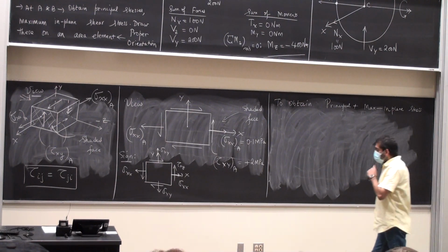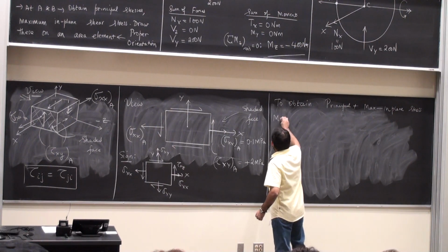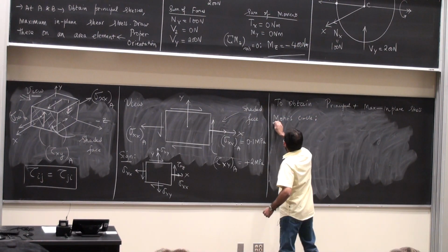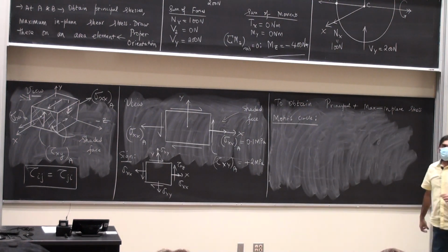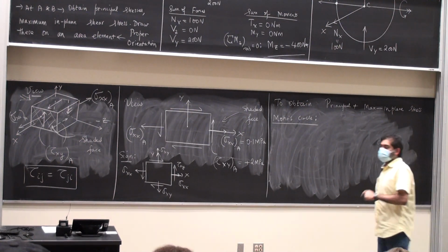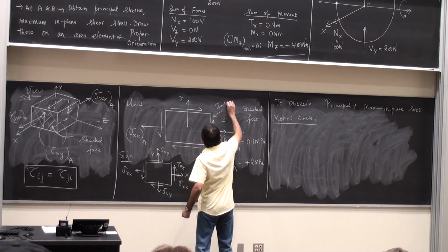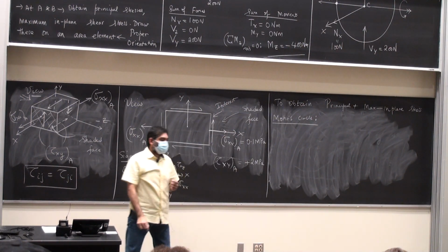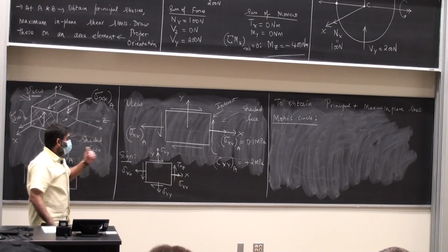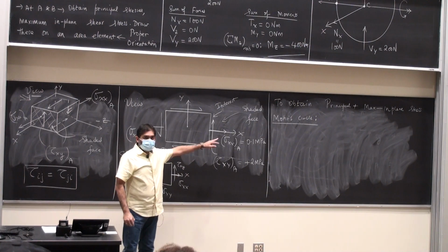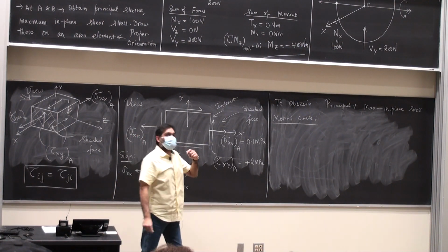Okay, Mohr circle. On my face of interest, this is the side of interest. We figured out together that based on the sign convention, these are all positive values. So I first write down the center of the Mohr circle.